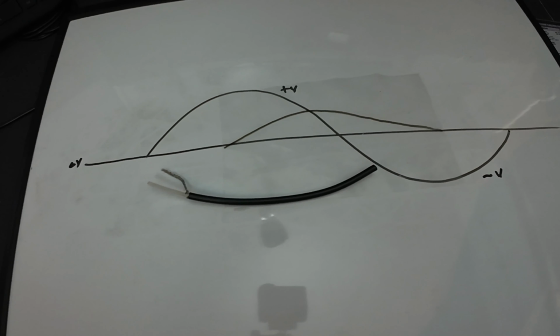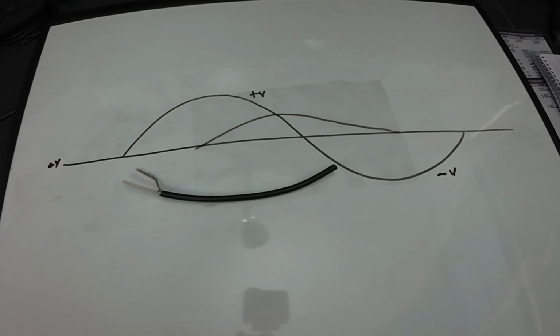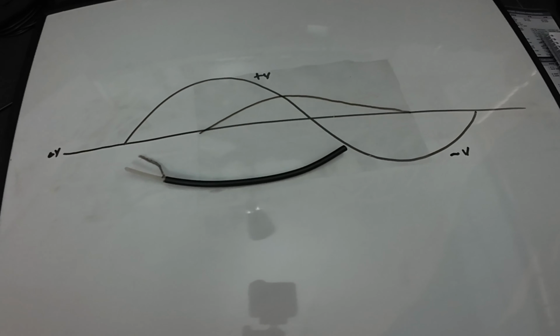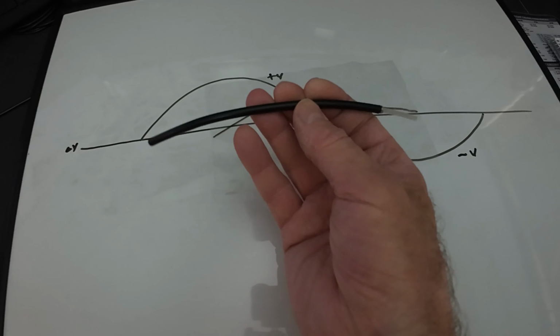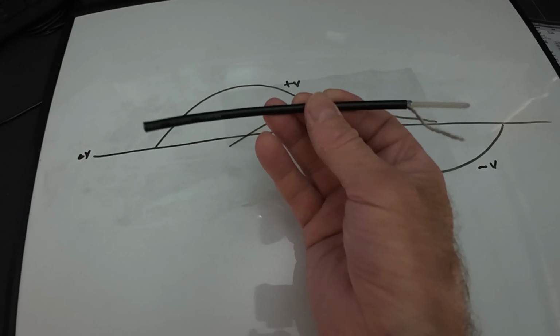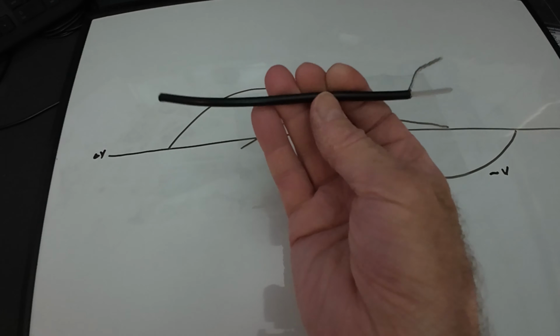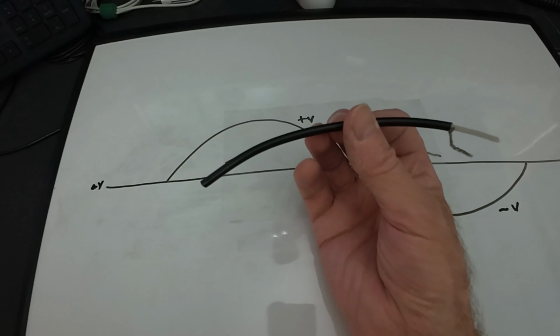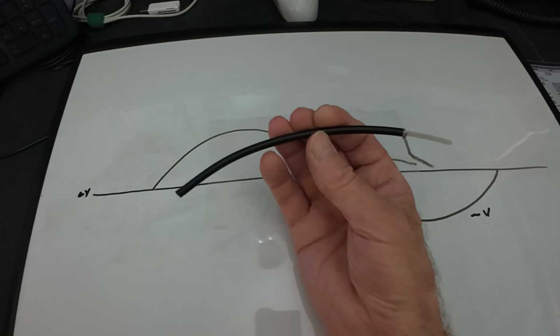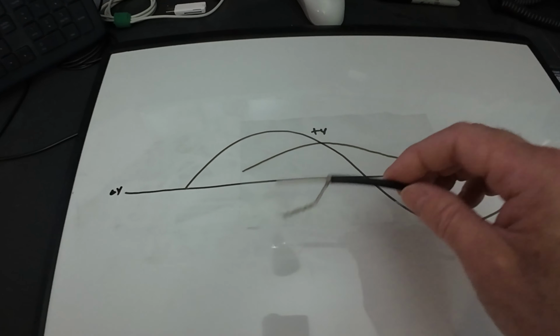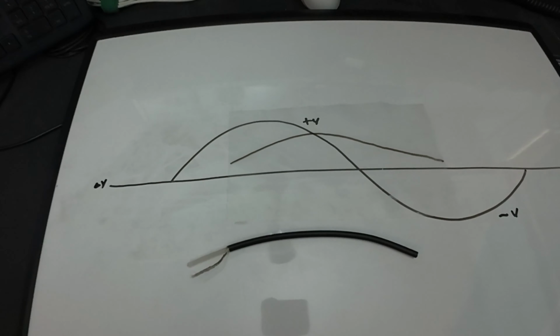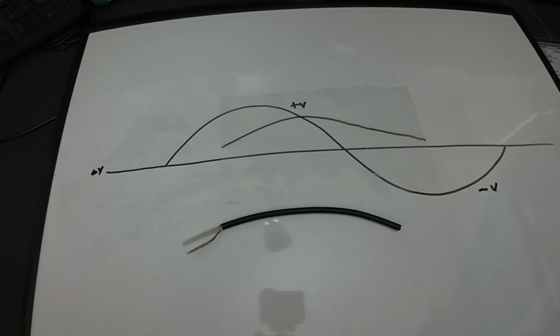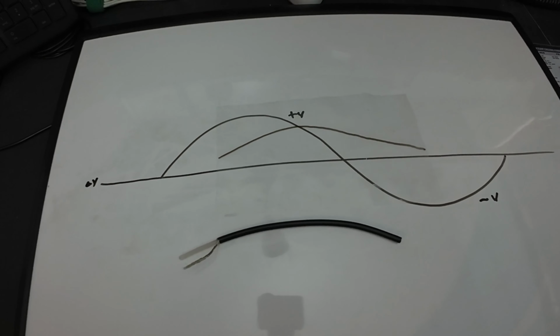And it's also measured in ohms. With a transmitter that's 50 ohms, a transmission line that's 50 ohms, and a load that's 50 ohms, we have 50 ohms impedance on all those devices. Impedance basically is a product of reactance in the transmission line. Reactance is what happens in an AC circuit when you throw in some capacitance or some inductance.